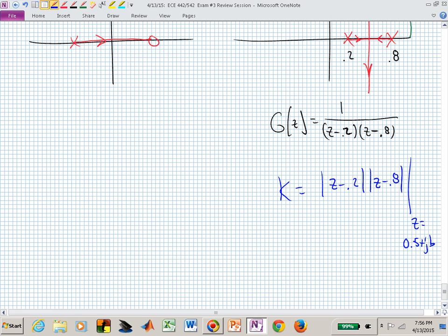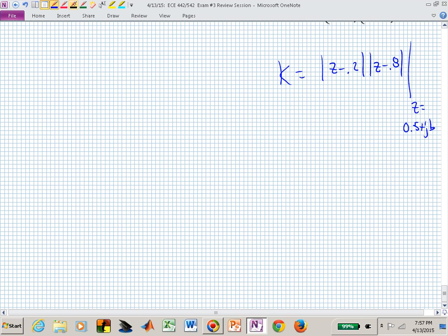And the magnitude of that complex number on the left should equal the magnitude of the one on the right because they're equal distance. Those are basically just hypotenuses from those poles to that triangle location intersecting the unit circle, as a check on your work. Is that clear? How you could find that? What else do we want to see for patterns?